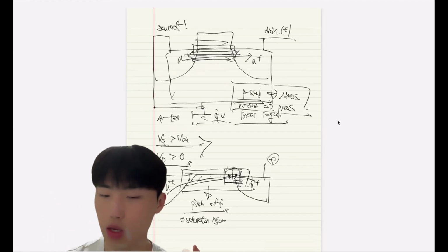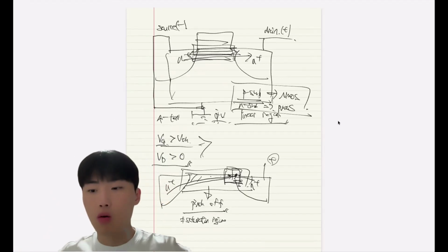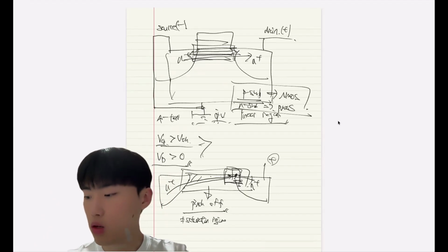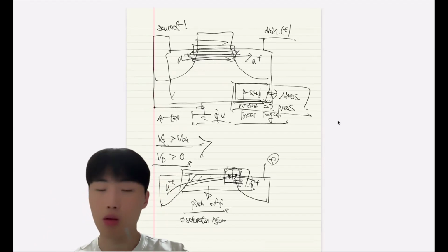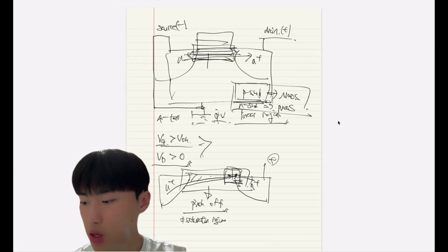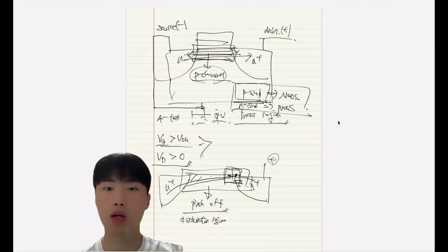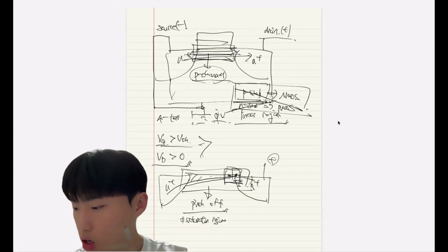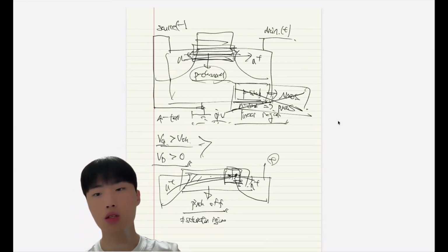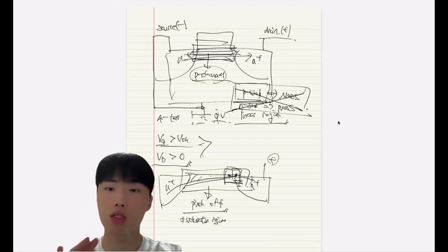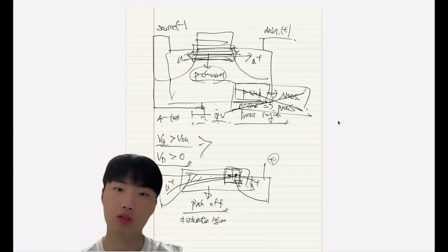I can give one example: when we use P sub, but we use the accumulation region we talked about in the last class, there will be a P channel. So it is PMOS, even though we use P sub. So this is the wrong knowledge about it. You should decide NMOS and PMOS by the channel polarity of the MOSFET.